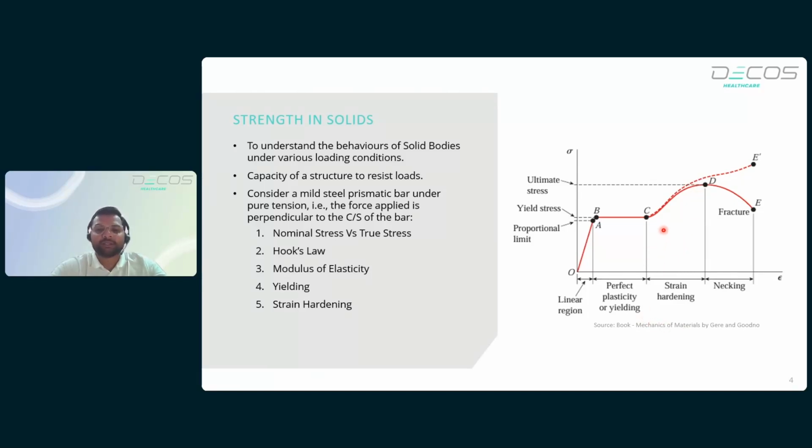Now, this is an important point, and it is significantly used in different manufacturing processes for hardening. Okay, so now we have learned what strength is, how a material under pure tensile loading behaves, and how it can be plotted. Right. Now, I would like to substantiate one point over here, that the failure of the material which we have discussed is under pure tensile loading. The body will behave completely differently if the loading is different. If it is not pure tensile loading, or if it is a combination of two, then the body may not fail in a similar fashion. Okay. The failure can be different.